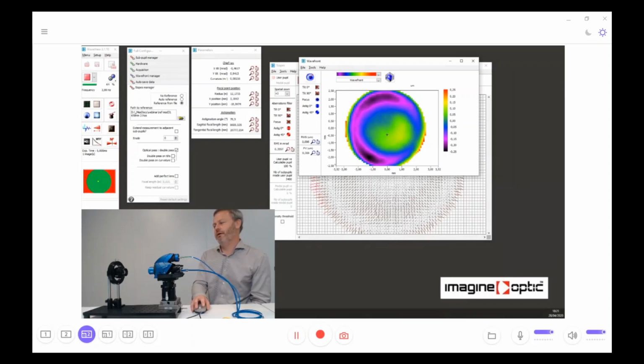One thing that I want to show you here is that, as Philip said, we're not in an optical lab here. It's simply a wooden table. We are in a meeting room. So if I hit the table here, the measurement is still feasible. That means that we don't need a very stabilized optical table as interferometry needs. It's not interferometry, definitely. It's Shack-Hartmann wavefront measurement, which means that the vibration can be huge. Even with the vibration, it's possible to do the measurement. This is an important thing to know.